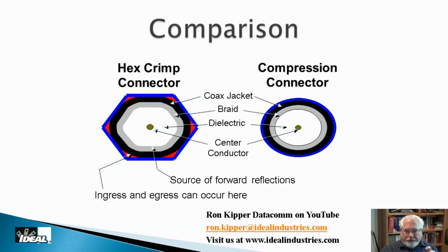And those little corners do a couple things. One, they let moisture get in and out of that connector, which I'm talking humidity corroding on a center conductor, which is a huge problem. And the other one is signal ingress and egress. Basically, signals can leak in and out of the connector. And as frequency goes up, we leak more energy. And these connectors are kind of considered leaky, so that's why your cable company no longer uses them.